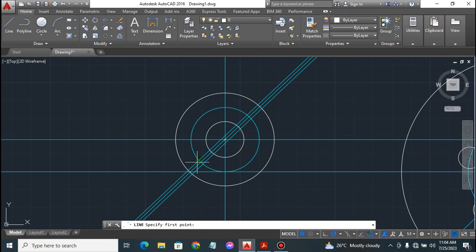All right, once you've done that, you simply lock your cursor to the point of intersection of this construction line where my cursor is right now, to reproduce the protrusions we are seeing from our PDF document. Then just left click on it, go to the next point of intersection and click on it, do the same here, then back to this point. All right, then click on it. So now we've succeeded in producing one protrusion, a replica of the protrusions we are seeing in our PDF document.